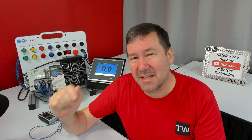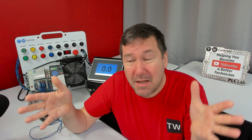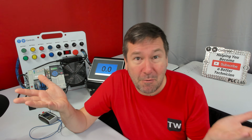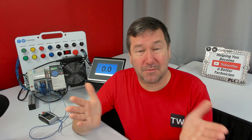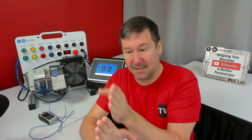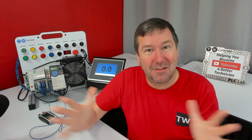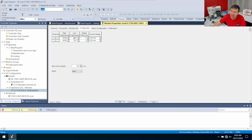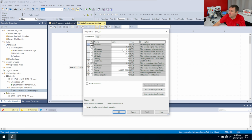But that's not the best way to do it, because as we make those units smaller, we lose resolution. In fact, okay, I want 4 and 20. If I put 4 and 20 in, I'm going to incrementally get 4, 5, 6, 7, 8, 9. And so I don't have that resolution, which is the point of an analog module. My min raw is going to be 3277, and my max raw is going to be 16383. I'm going to enter those right here.